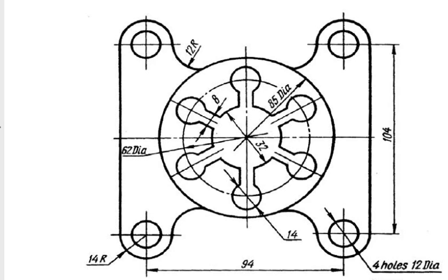The second thing is we have to know where to fix the origin. This particular figure is an axis symmetric figure, so I'll take the origin at the center. If you want the figure to be only in the first coordinate, then generally we give the lower left corner limits as 0,0 and specify the upper corner limits. But here, as it is an axis symmetric component, I will take the limits as minus 100,100 and plus 100,100.